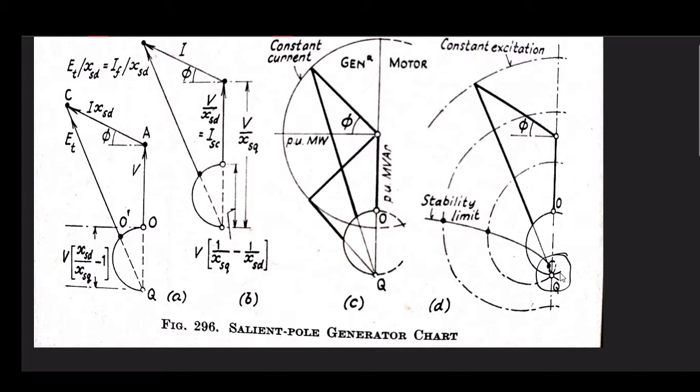In the words of MG Say, using a good technical term, we have a limaçon here, instead of concentric circles, and the shape becomes more evident with small excitation, which gives birth to this reentrant loop.